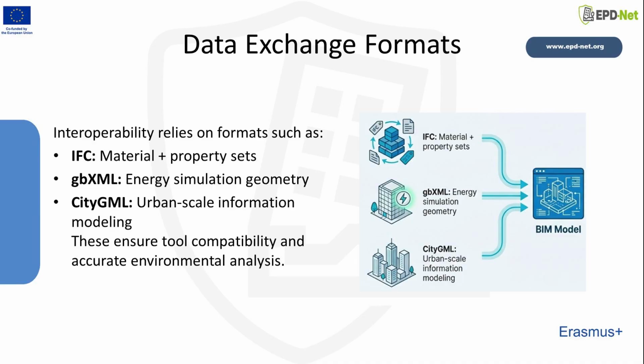Interoperability is essential for connecting BIM models with specialized environmental tools. IFC enables rich data transfer, including geometry, material assignments, property sets, and classification codes. GBXML supports energy modeling by translating BIM geometry into simplified thermal zone representations compatible with simulation engines.